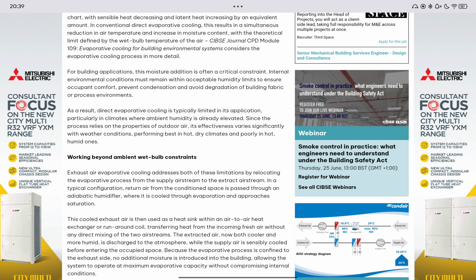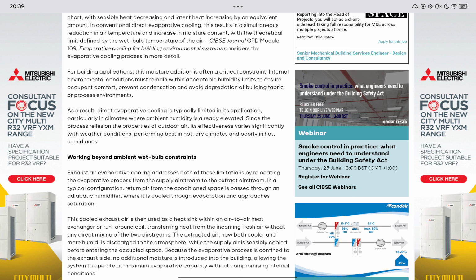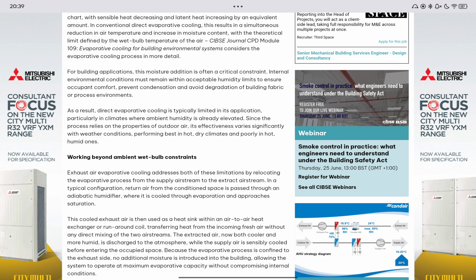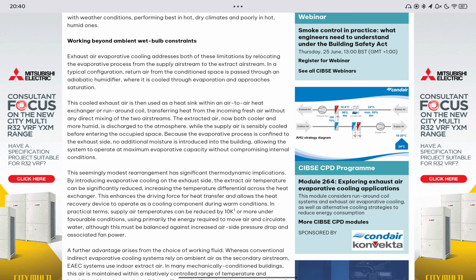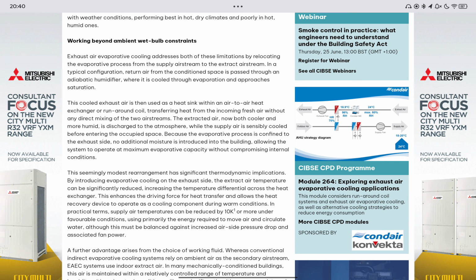Since the process relies on the properties of outdoor air, its effectiveness varies significantly with weather conditions, performing best in hot, dry climates and poorly in hot, humid ones. Working beyond ambient wet bulb constraints.